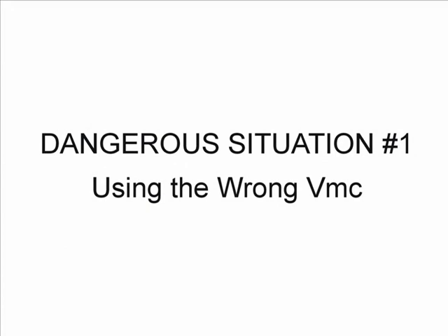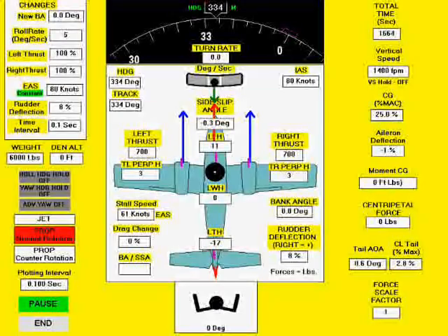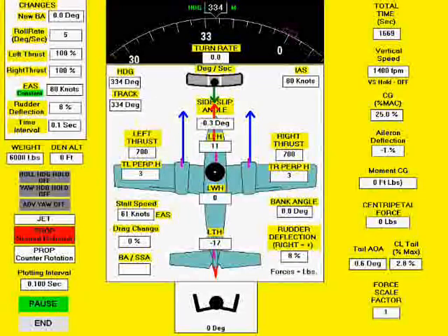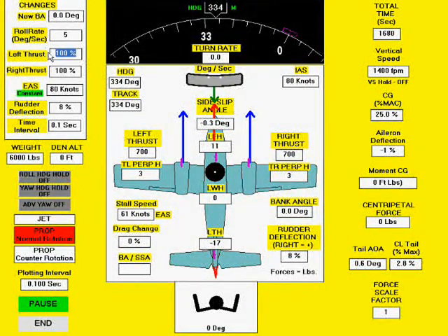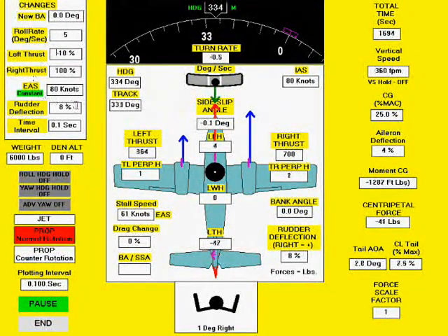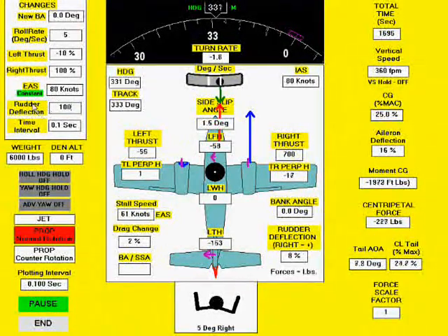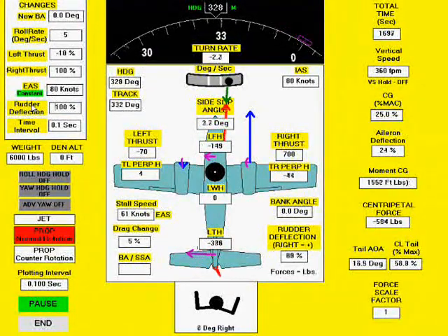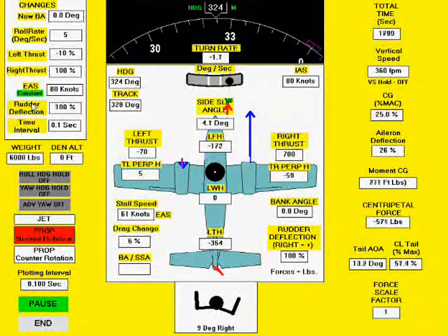In this example, the pilot operating handbook lists VMC as 73 knots, with no further information. Applying a common rule of thumb, we add 10% to find the minimum initial climb speed, which is 80 knots. We are now in an 80-knot climb with the wings level when the left engine fails. While maintaining a wings level attitude, we apply 100% right rudder deflection, but the turn rate continues.